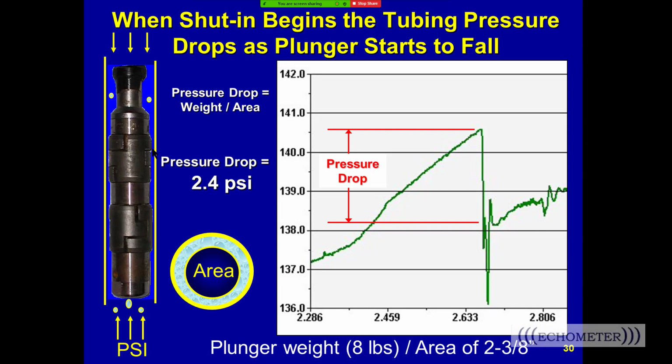Conventional plunger lift doesn't like packers. Gas lift likes packers. So a lot of times when your well starts to deplete, you want to convert the well from a flowing well with a packer to a well without a packer, because you want to use the casing annulus, and it's going to cost you money to take the packer out. So you might try to be low cost and shoot a hole through the tubing to use the casing annulus.